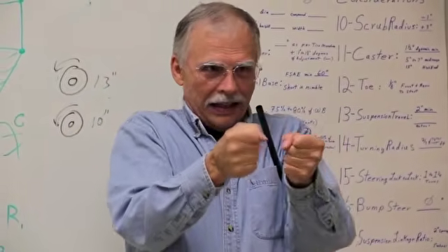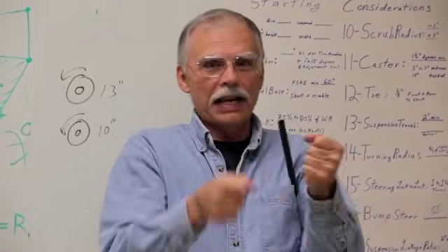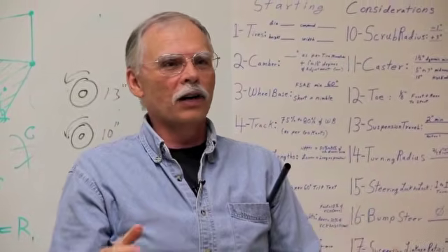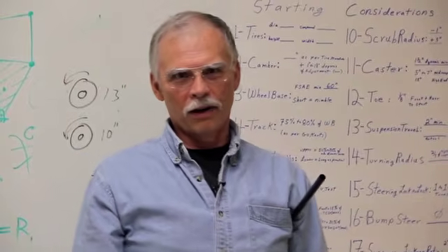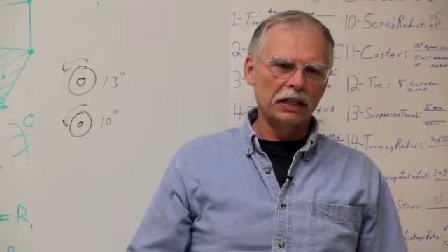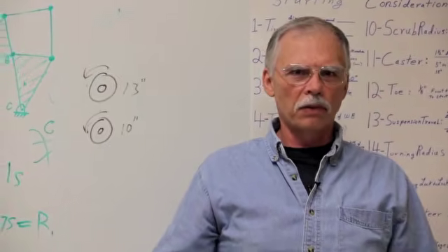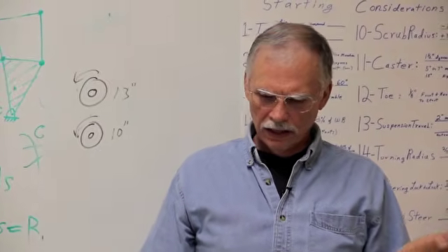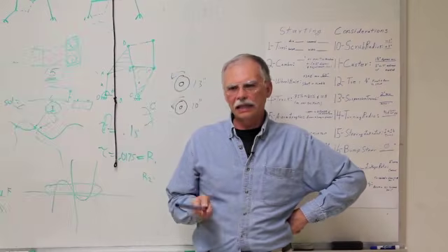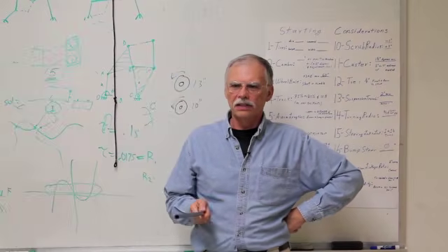Simple little things like an adjustable heel stop so the driver's foot doesn't slide around in there when he's modulating the gas can drop a second or two off a lap. Just nothing but a little heel stop. Little things like that. So look at your driver's ergonomics. This is probably the most neglected thing in FSAE design.